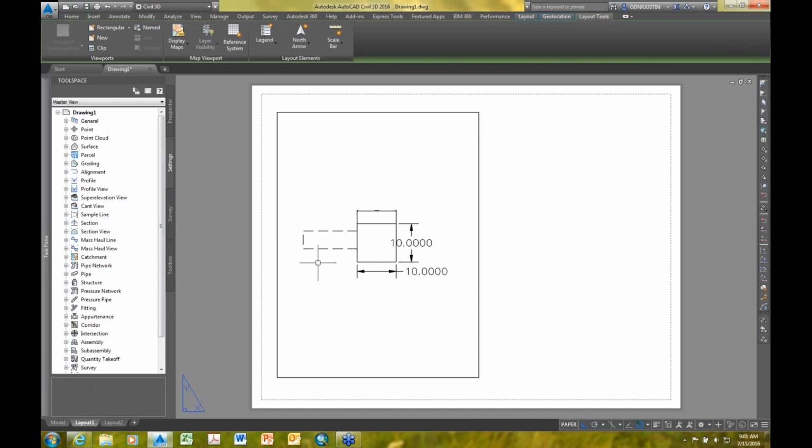And like I said, it's pulling that scale from your model type. So anytime you start to type in a command, it'll pull that text right up there. Paper space, line type scale. Right, there's that command. It's set to 1.